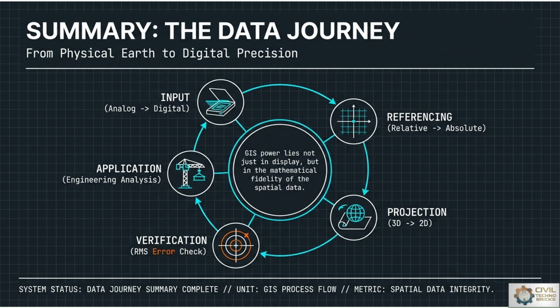From the civil engineering point of view, we often digitize old utility maps to understand existing underground networks before a new excavation starts. So before excavation, we can use that scanning and digitizing activity based on the GIS data. While convenient, these secondary sources must be carefully georeferenced to ensure they match the correct projections or the ground control points, based on the projected coordinate system and precision requirements.